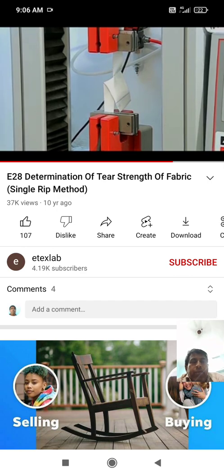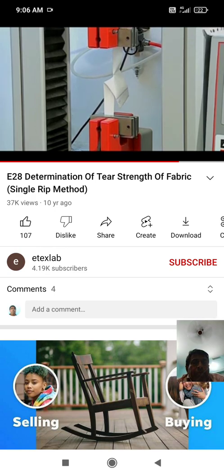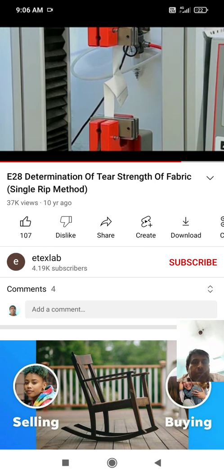One must make sure that there is no slip in the jaws when the sample is tested. One jaw is movable, one jaw is not movable. The tear must be linear. Test results are not taken into account if the shearing is not linear and if the jaws slip.